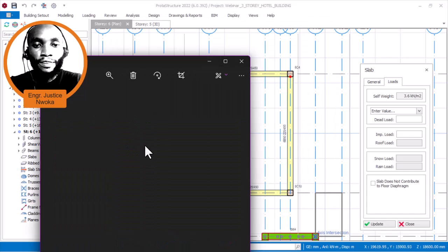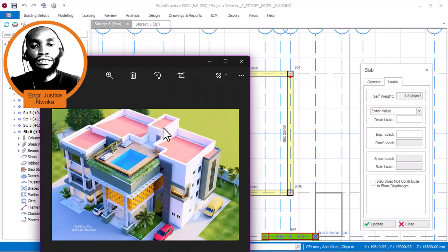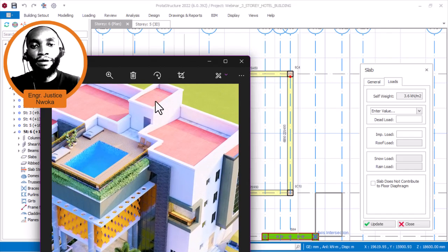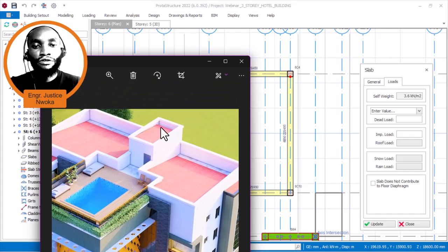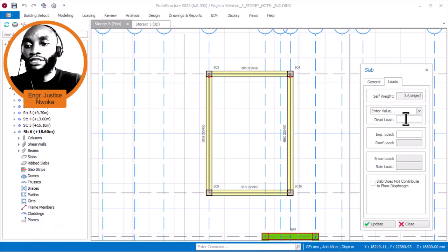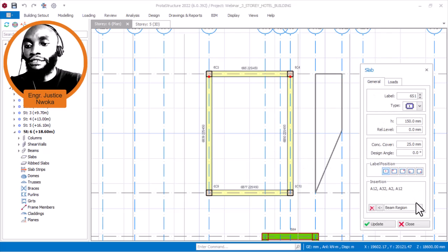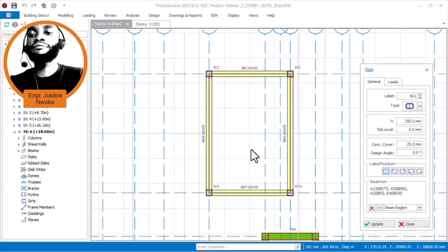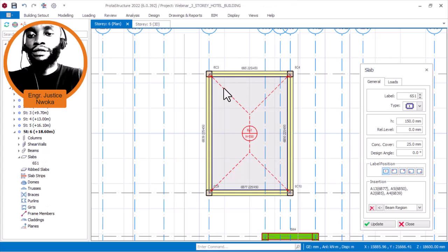Let's see that. Okay, so you can see that even the slab is going down by some values. But basically you can just allow that to happen because this is just for covering. So let me just allow that without putting any value. Then I put 1.2 because that's just a roof load. Then here I'll put 1.5, then insert my slab there. Okay, that's fine.